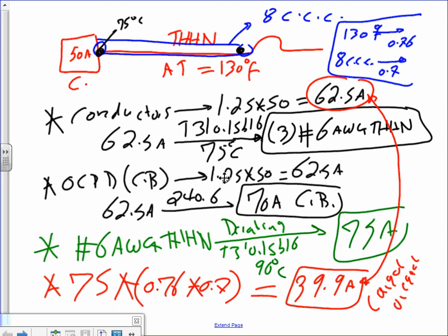The exception is low voltage. Why is that? Because paralleling is inherently dangerous because of the length and the requirements and what's not. If you start paralleling smaller conductors, you expose yourself to more danger than you need to. The reason why we parallel, guys, is because the conductor becomes big. 1/0 is big enough. If it's anything less than 1/0, you shouldn't parallel.